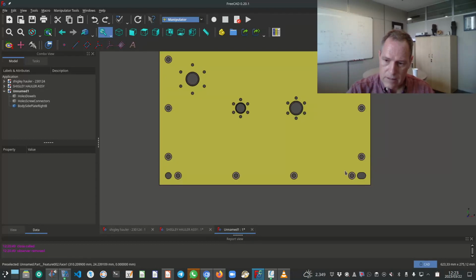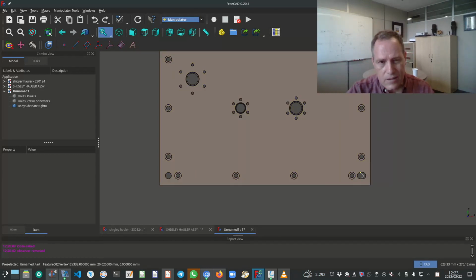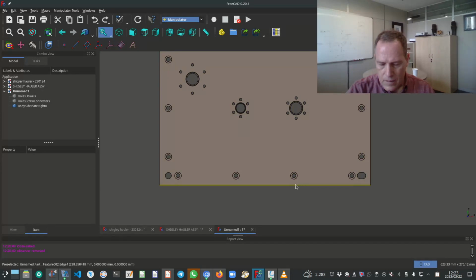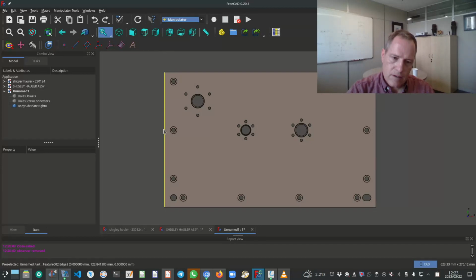In the vertical direction. In the horizontal direction, a plus minus tolerance will suffice, because the length of the slot isn't that critical. We can have a tolerance there, but in the vertical direction, our placement of the slot is critical. So there we will once again use a positional tolerance from this bottom datum. And I said earlier, let's select this face as the secondary datum, the bottom face as the primary datum.